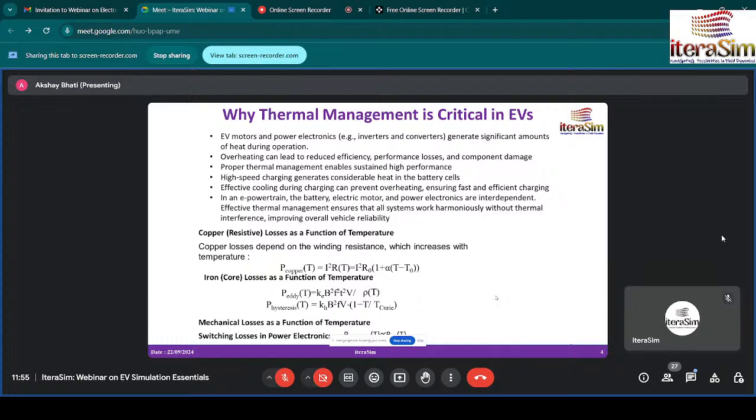If we talk about Tesla, earlier for the high power segment, it was using spray cooling for cooling the end winding. But nowadays they have shifted to another approach. They are using gravity and some suction created by the RPM of the motor to make the machine more efficient. So there is still research going on in this field.